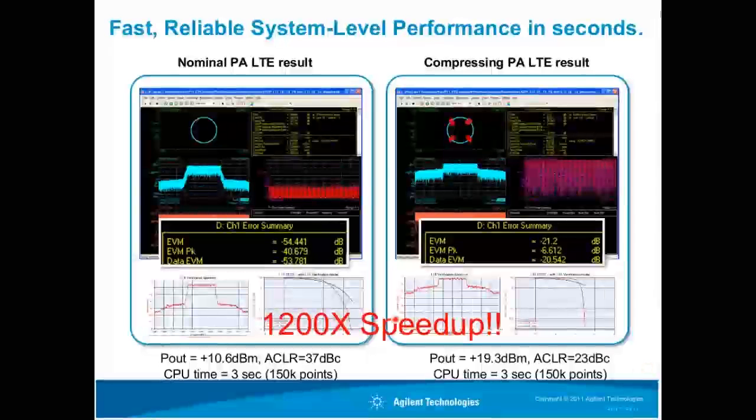And as I mentioned, I've run this example in co-simulation form. So compared to doing a co-sim where you have a pipe open to the Linux side, so you can run your system level tools at the same time, this sim takes about an hour, so that's about a 1200x speed up over doing co-sim. And again, that's for a small circuit. So the speed up for a big circuit is going to be much higher. If you're running a receiver or something like that, you're going to find that co-simulation is not really even an option. It's good to have the option for the small circuits just to do verification that your model is working well.